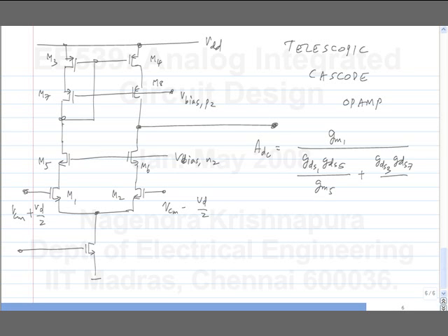And we know the transconductance, it's the same as before. So, let's say you had a load capacitance and you had the simple differential pair op-amp driving the load capacitance. You replace that with the telescopic cascode op-amp. What happens to the unity gain frequency? It's the same. Okay. But the DC gain increases.